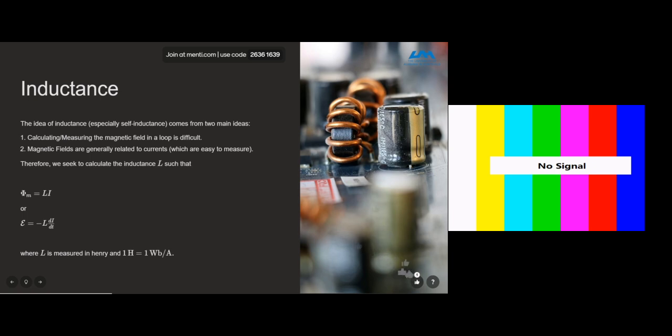So you connect an inductor to a 9-volt power supply and you turn on that 9-volt power supply. It is not going to go from 0 to max current in 0 amounts of time. It will take a certain amount of time for that inductor to have the current ramp up to full strength. And the reason is as the current changes inside of the inductor, it changes the magnetic field within the inductor, which causes a back EMF.